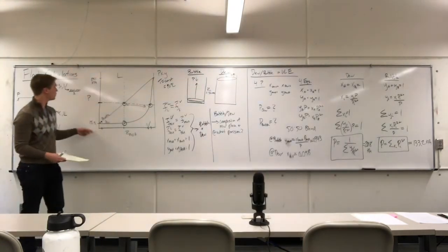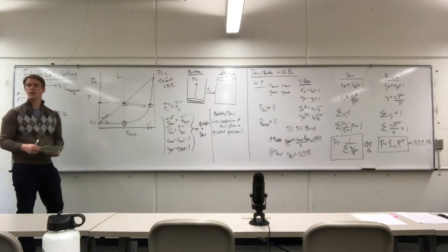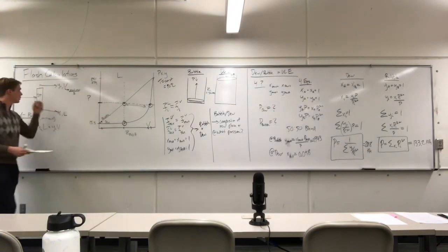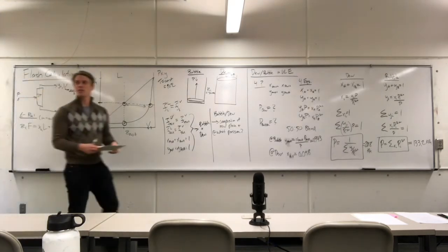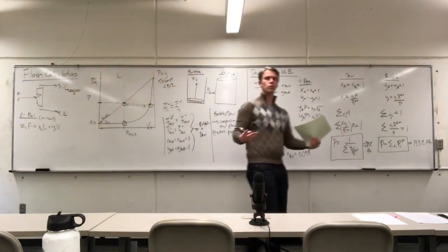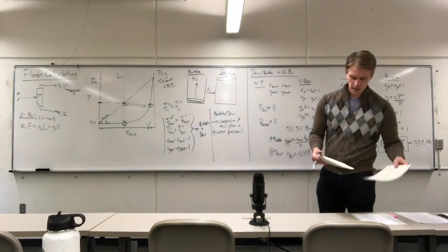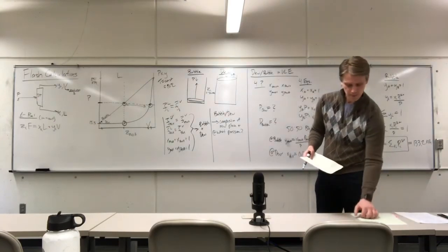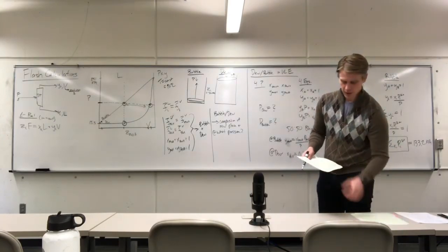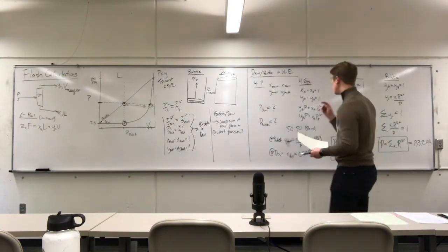In this case, these two have some fairly large differences in relative volatility. So a flash drum like this, you're really only going to see in a chemical plant when you're separating gases from a liquid, or something that's extremely volatile from something that's non-volatile. Anything else more advanced than that, then you're certainly going to have to use a distillation column. Questions on flash calculations?